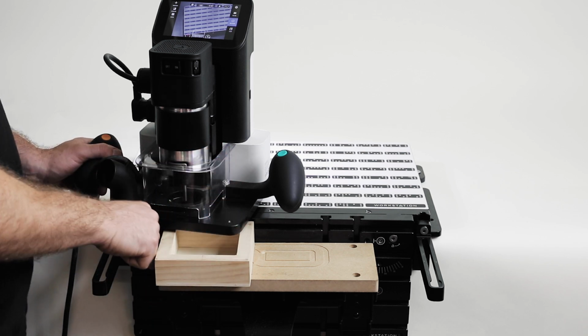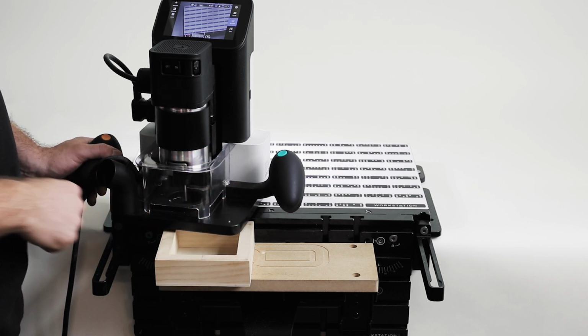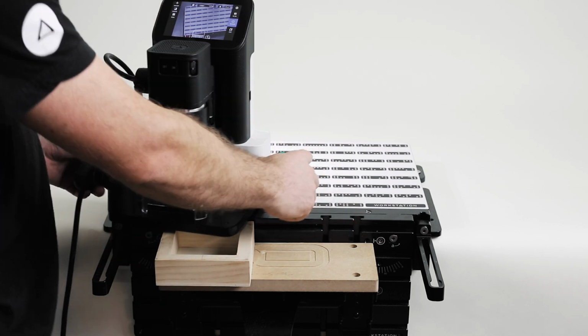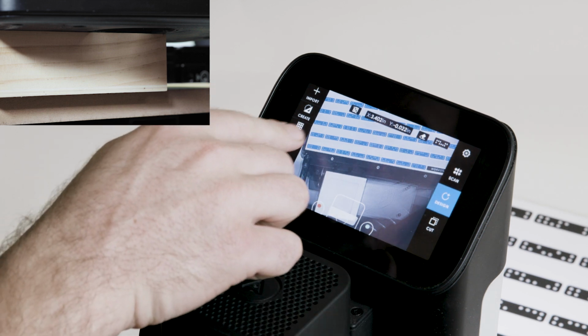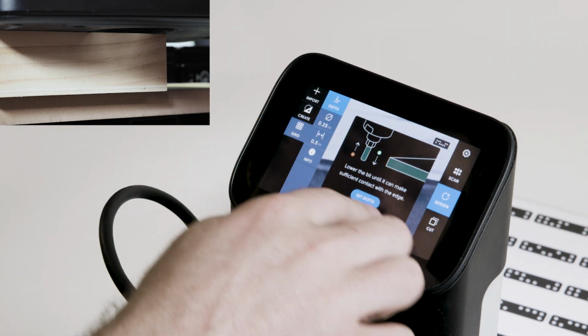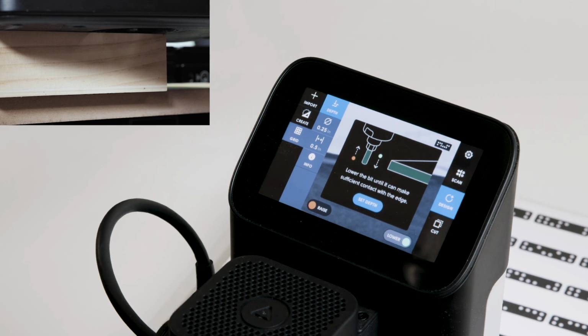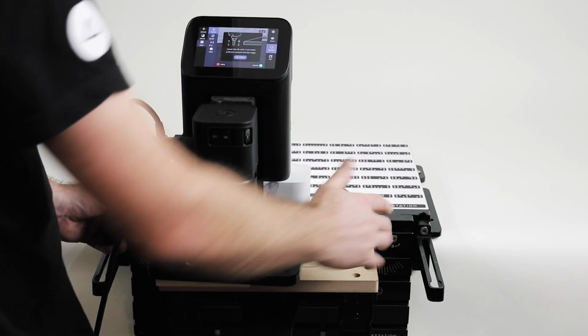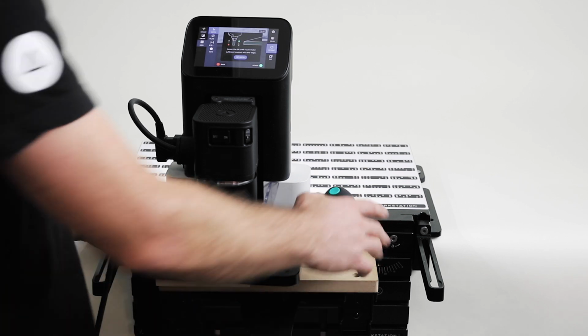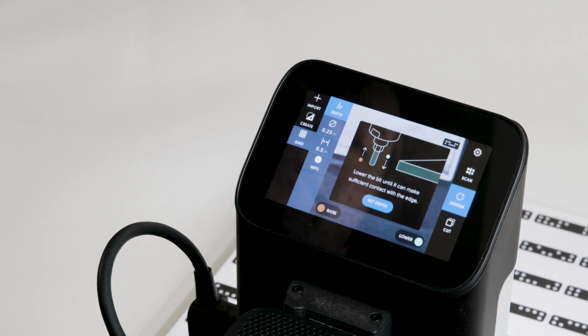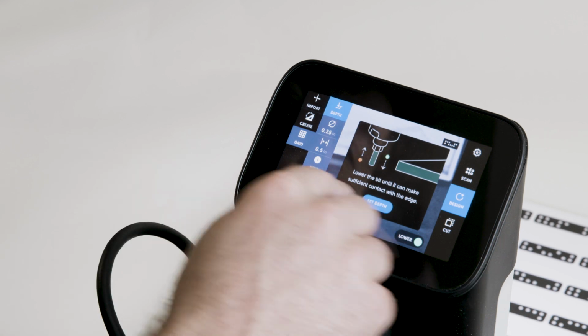First we'll start with the standard basic grid where we just physically probe these 3 positions as seen in the info screen. Come over to this point. I'll go grid, new grid, and then we'll lower it. So I'm just confirming I'm off the edge and that the cylinder is going to contact my stock as I move it inwards. Once I'm happy with that, I set depth.